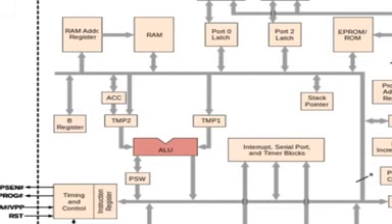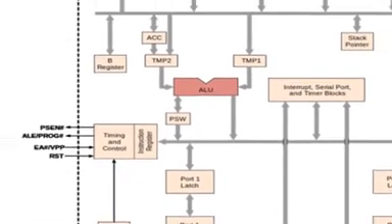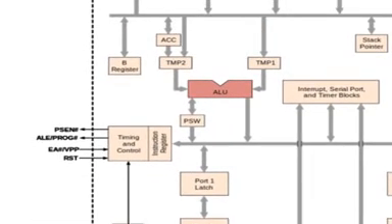For multiplication, after execution the result is stored in A; if it is a bigger number, the lower byte is stored. In division the quotient is stored in A. And B is also an 8-bit register: in multiplication the higher byte is stored in it after execution, and for division the remainder is stored in B.